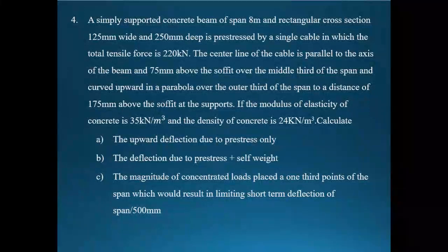Everyone, welcome back. Today I'm going to explain a problem on deflection. A simply supported concrete beam of span 8 meter and rectangular cross section 125 mm wide and 250 mm deep is pre-stressed by a single cable in which the total tensile force is 220 kN.